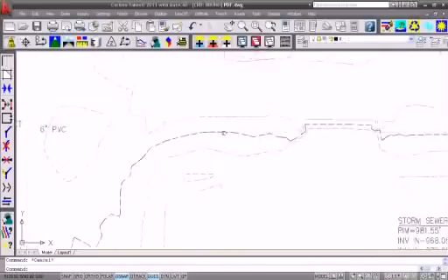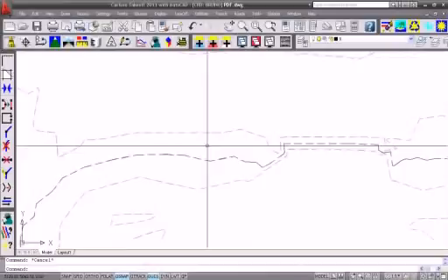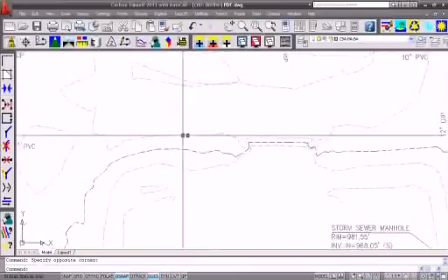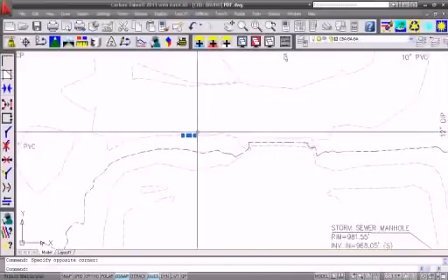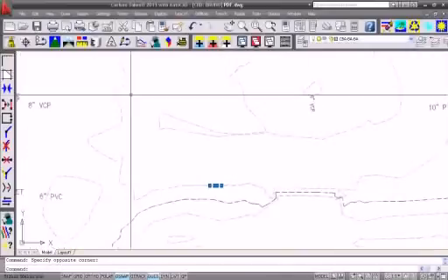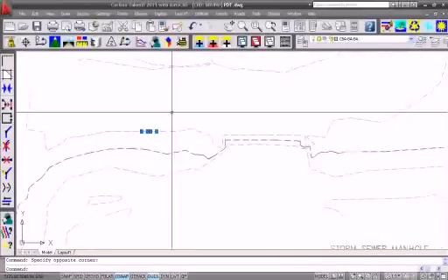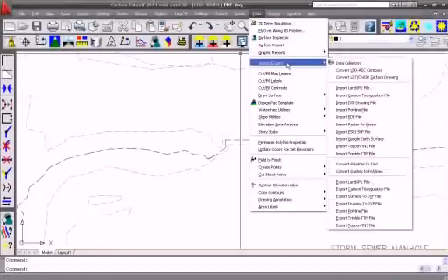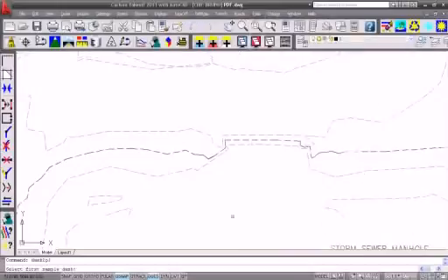Now, when we change those segments to solid lines and we get rid of the blue bars, are we downsizing the file at the same time? It would probably reduce the file size because we're going to have less points comprising the contour lines. That's something we can look at. But the new routine is under Import Export, and I'm going to say convert dashes to polylines.